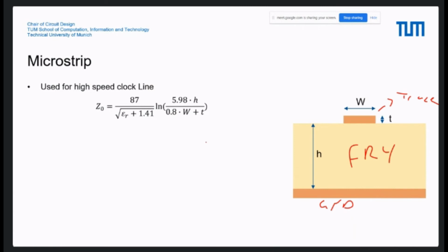So the important thing to know is that if you have short lines, it means you don't need transmission lines. The energy is delivered by the trace, so it flows here. But if you have long traces, then you generate a magnetic field and an electric field. So the energy transport is then not in the trace, but in the cover. The energy transport is inside the FR4. And therefore, we need the theory of impedance matching. I think you learned it also, or it's called the Poynting vector.